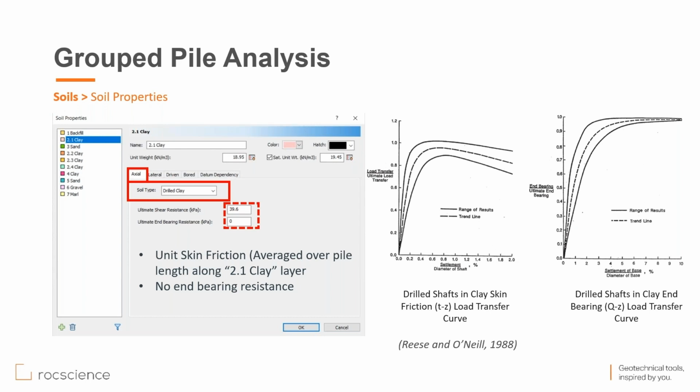Unlike the RS3 or RS2 finite element models, you don't have the option to just directly model the cap and the raft and the soil in an integrated manner. So it's some sort of a decoupled analysis, where you can use the results of RSPile and plug them back into a finite element software to continue if you wish, or you may just finalize your detailed structural design with RSPile as well for typical problems.